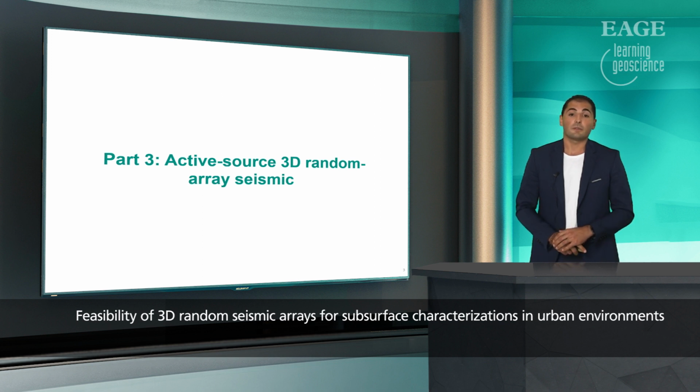However, could we have done the survey differently and obtained similar results without the conventional 2D seismic method? With this in mind, we exclude all the data recorded on the landstreamer and focus our analysis on the GPS time-tagged source locations activated along the landstreamer and recorded only on the wireless seismic nodes at the site. Essentially, the question here is if we could resolve the bedrock morphology if we deploy our wireless nodes in a random manner, take our seismic source, drive it around, activate along the streets or pedestrian pathways wherever possible, and obtain a similar seismic image.